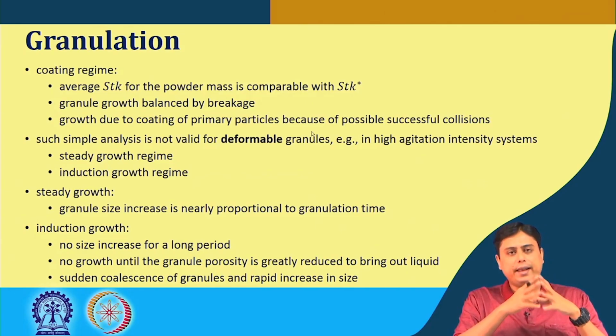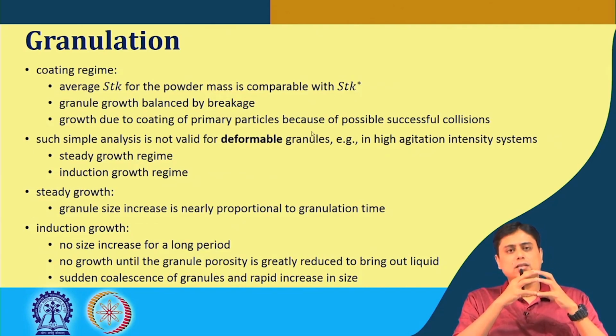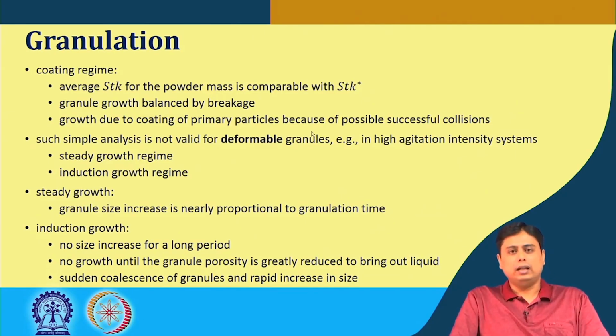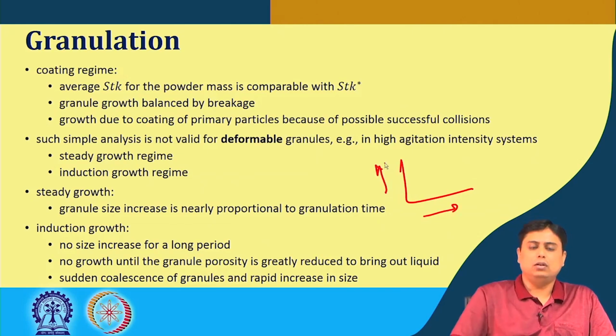Now, this simple analysis does not work if the granules are deformable, and that typically happens in high agitation intensity systems. In that case, two different regimes have been identified. One is the steady growth regime, the other is the induction growth regime. In the steady growth regime, the granule size increases nearly proportional to the granulation time. So, if you draw a graph of granulation time and granule size, it increases linearly.